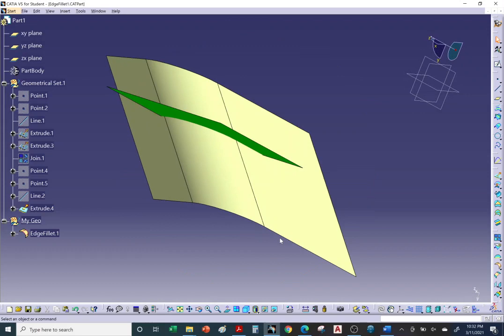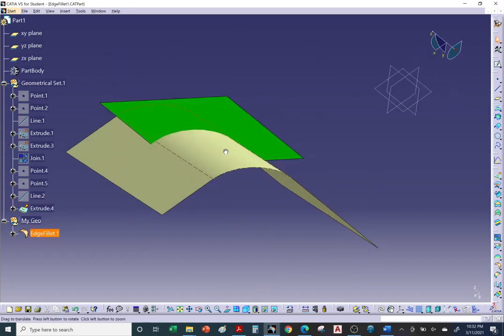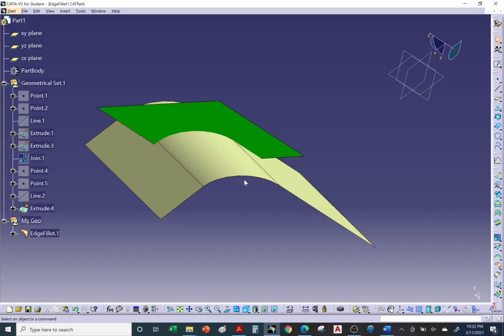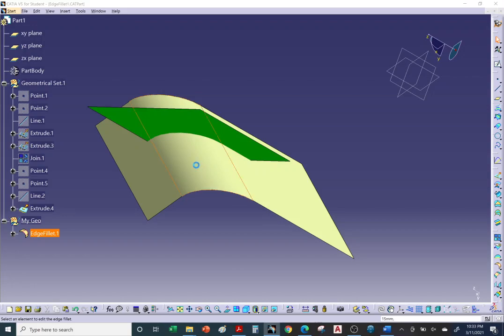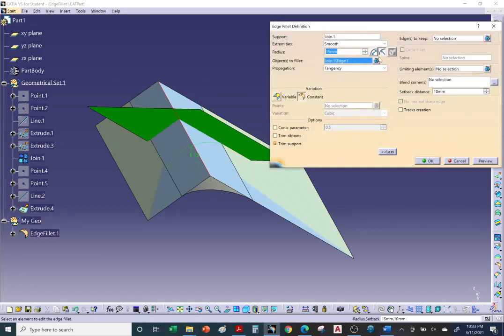And very similar to shape fillet. So the difference is, on the previous video, shape fillet, it was two separate surfaces. On this one, it's one joined surface, and we pick a sharp edge to fillet. Okay, and very similar to shape fillet. Just like we have a radius fillet, we can also go with the quarter fillet. In this case, 15 millimeters is the distance from the tangent line to the other tangent line. And preview, so again, 15 millimeters from one tangent line to another.